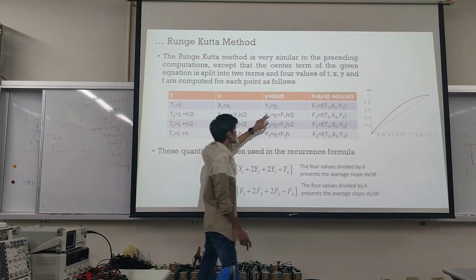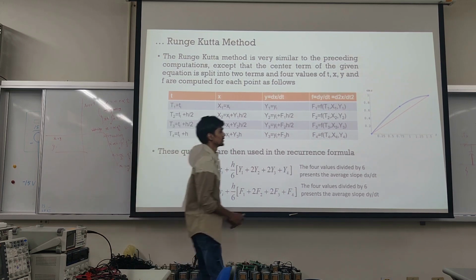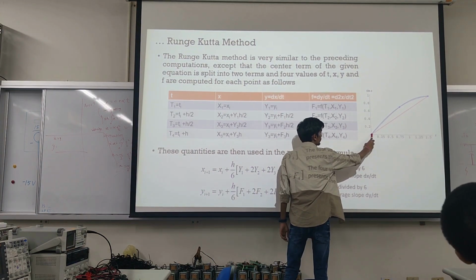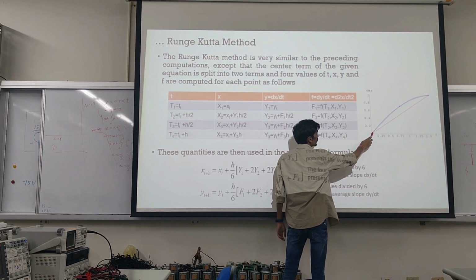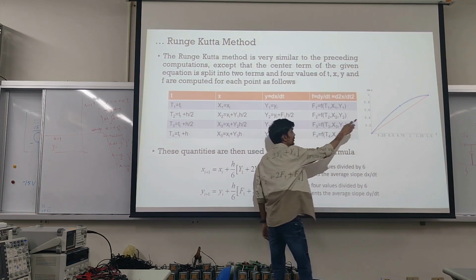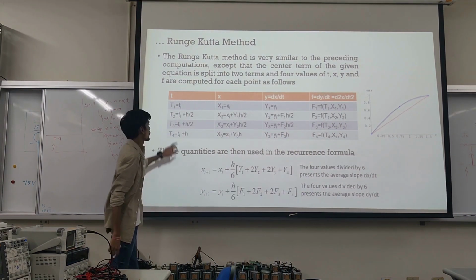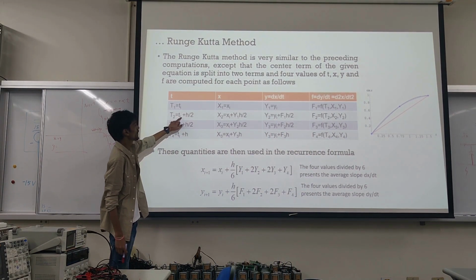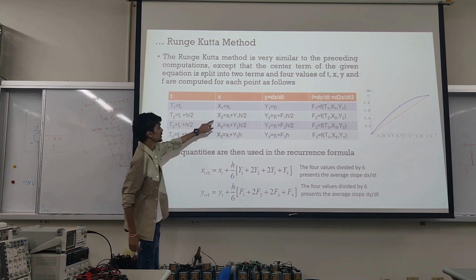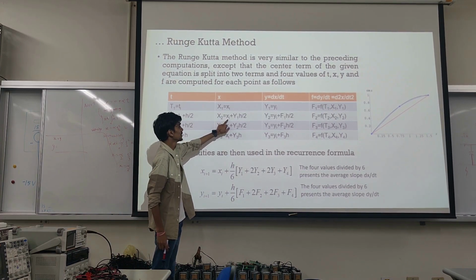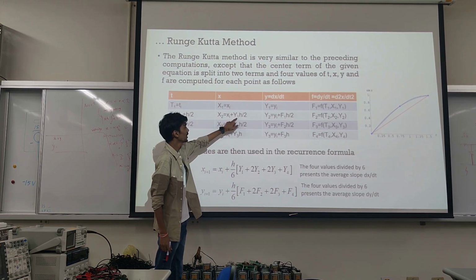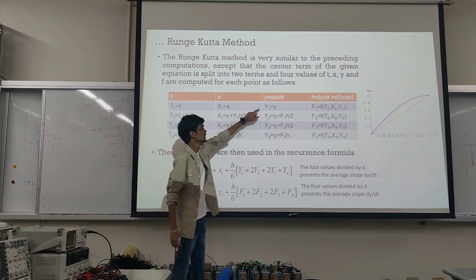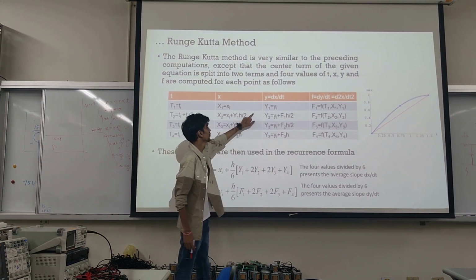Now at the first step we have the time. We already know displacement and velocity, and now the acceleration also. So from this step we will get the first middle term at t2, which is ti plus h by 2. Then x2, that is our displacement, is xi plus y1 into h by 2, where y we get from the velocity.